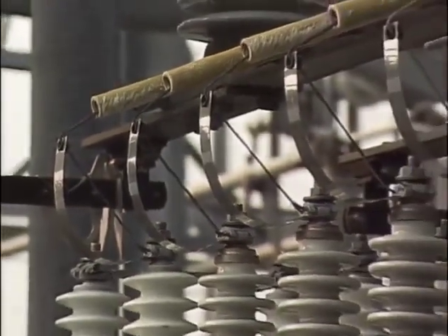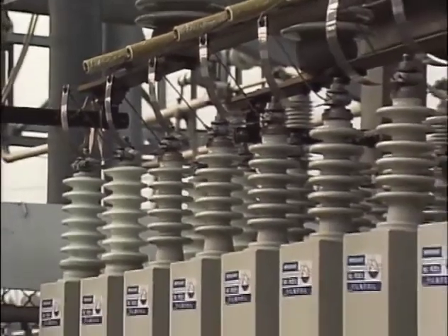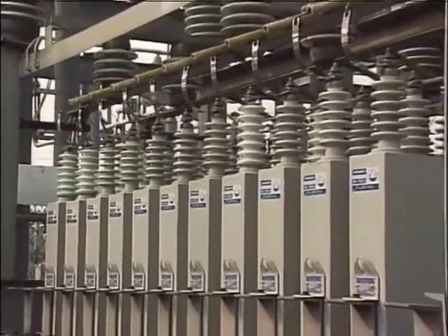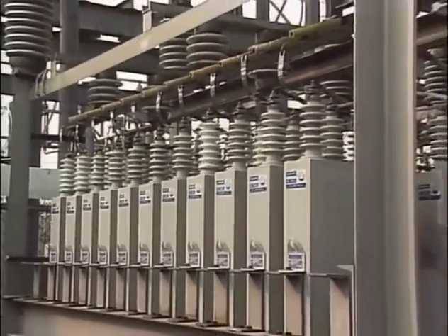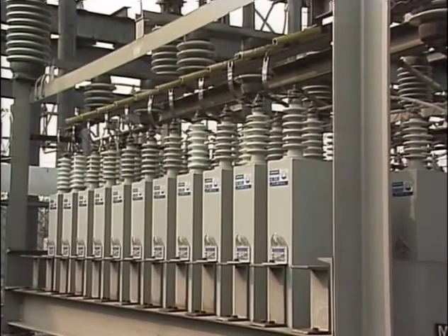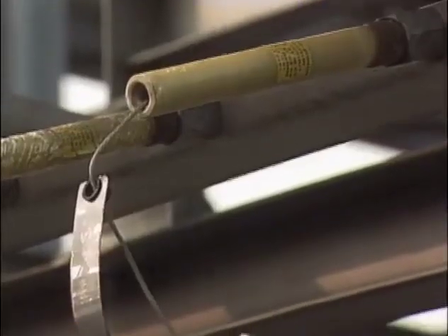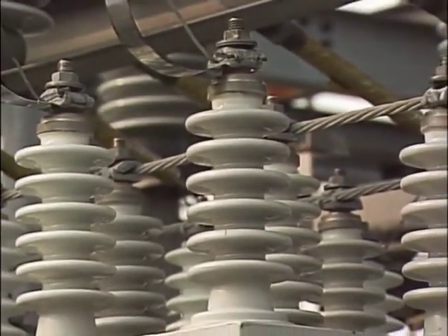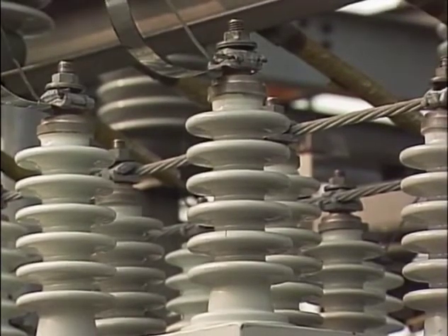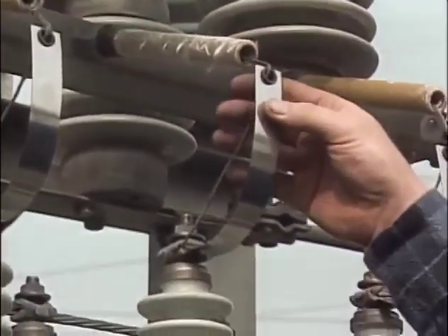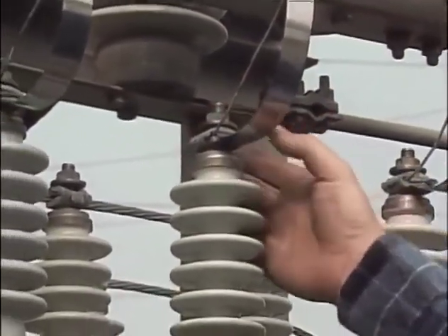Failures more commonly occur at individual capacitors and capacitor fuses. Typically, both are visually inspected on a regular basis. Each capacitor in a bank is protected by a fuse. If a disturbance occurs that might damage the capacitor, or if the capacitor fails, the fuse should blow to disconnect the capacitor from the bank. During an inspection, the fuses and fuse connections are checked to make sure that they are not loose, frayed, or corroded. If any part of a fuse or its connections appears to be deteriorating, it's better to replace the fuse than to wait until it blows.